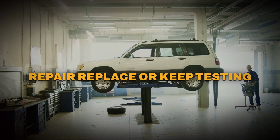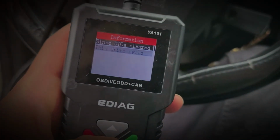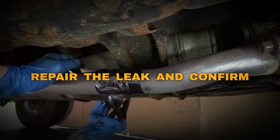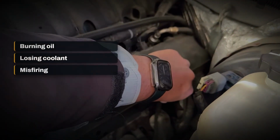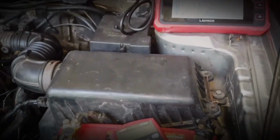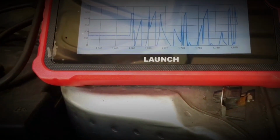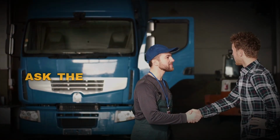Repair, replace, or keep testing. Here is the complete diagnostic order. If P0420 appears with misfire, fuel control, temperature, or sensor codes, diagnose those faults first. If there is an exhaust leak, repair it and confirm that the leak is gone. If the engine is burning oil, losing coolant, misfiring, or operating too rich or too lean, repair that condition before installing a converter. If the oxygen sensor signal or circuit is unreliable, diagnose the sensor system. If all of those areas test correctly and the catalyst repeatedly performs below the vehicle's threshold, the converter becomes the most likely repair. Before approving replacement, ask the shop these questions.